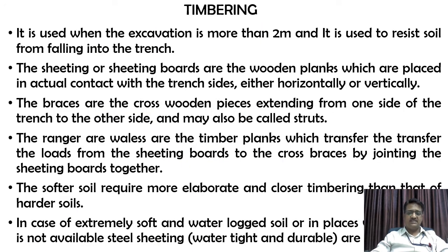Now, the next part is timbering. Timbering is nothing but providing the braces for that excavated depth or trench, so that we can have safety for the workers who are working there. It is used when the depth of excavation is more than 2 meters, and it is used to resist soil from falling into the trench.